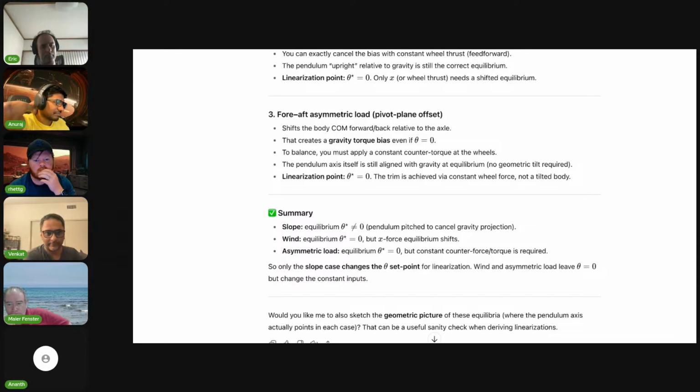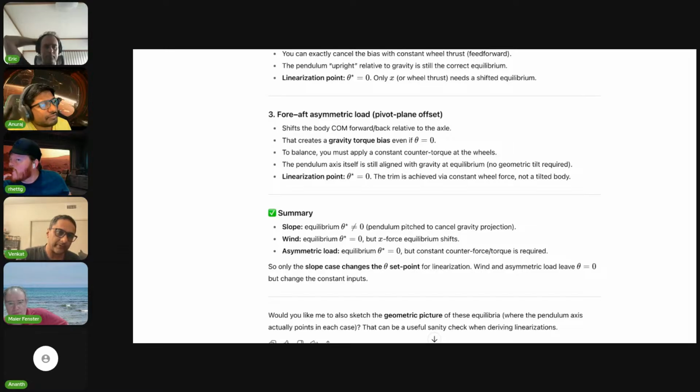Think of it as a fixed arm that carries a fixed load, which is the caster wheel. It's fairly low down, whereas a manipulator arm would be higher up, but it's the same kind of model accommodations that are needed. So just to look ahead a little bit, I believe we should be able to rewrite the controller to do balancing even with the asymmetrical loading of the tail and the wheel. So it should be able to balance even then by leaning back a little, basically.